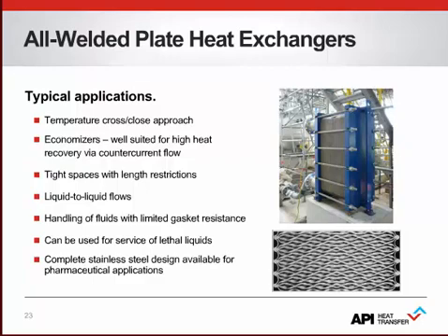When the gasketed plate heat exchanger cannot be used due to pressure, temperature, or the aggressiveness of the fluids for the gasket, then an all-welded plate heat exchanger comes in the picture. Therefore, the typical applications are similar to gasketed plate heat exchangers, but with a focus on chemicals and pharmaceutical industry.